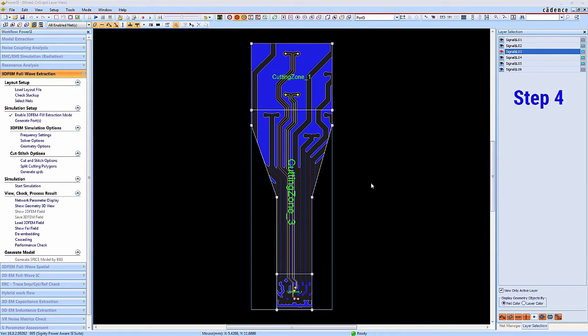We're now at step 4, which is mixed solver cut and stitch simulation. To save time in the demo, I took a few minutes offline to set up most of the analysis, but we'll review before launching the simulation. First, I crafted a more conformal cut region for the local simulation. I verified it maintains the same level of correlation we observed for the quick and dirty rectangular cut. Then, I set up 3 zones by defining 2 cut lines.